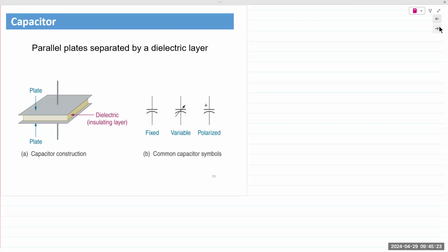Especially a cable will have 2, 3, 4 multi-strands going through it, right? A standard USB cable has 4. Plus and minus in the data cable, at least 3, if not 4. Okay, there's data plus, data minus, plus 5 volts and 0 volts. So there's at least 4 in there.